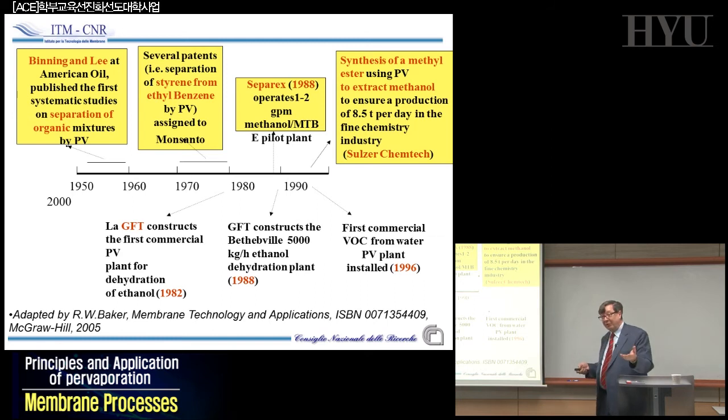However, industrial pervaporation, not the one of Abbé Noël, was invented a little bit later, and the first studies started in the 60s, in the same period as reverse osmosis. Only in the 1980s, GFT in Germany, and also Sulzer, started to produce commercial systems for alcohol dehydration, because that was the big problem at that time. Those were the easiest membranes: hydrophilic, where water went through and you concentrated the alcohol. But now the new area, where most of the new applications are attracting attention, is this one.